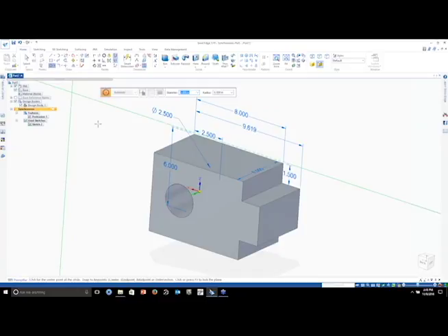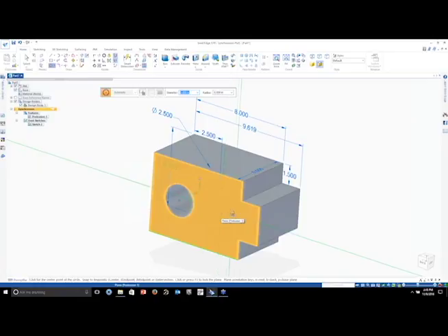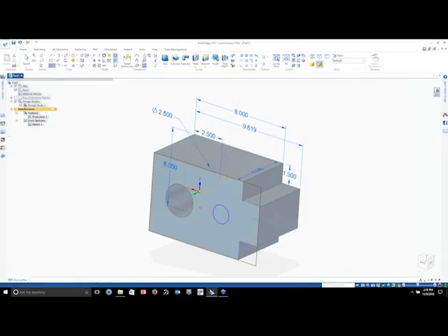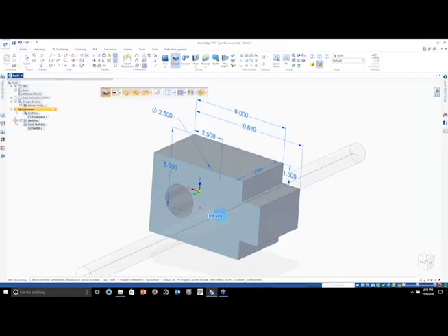All right, so the first thing you notice is my sketch that I used to create the geometry is thrown into a folder called Use Sketches. Every time you use a sketch in Sync, for example, if I want to draw another cutout on this, I'm going to go ahead to my circle. In this instance, instead of locking to the reference plane, I want to lock to the front face. So I can either hit the little lock with my cursor and click it, or hit F3. So I'm just going to go draw a circle here.